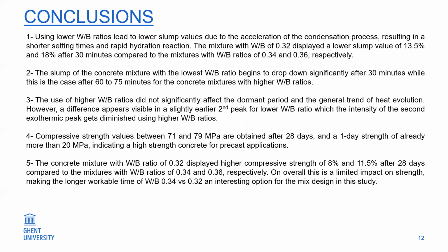Compressive strength values between 71 and 79 megapascal are obtained after 28 days, and 1 day strength is already more than 20 megapascal, indicating a high strength concrete for precast applications. The concrete with water to binder ratio of 0.32 displayed higher compressive strength of 8% and 11.5% after 28 days compared to the mixtures with water to binder ratio of 0.34 and 0.36 respectively.